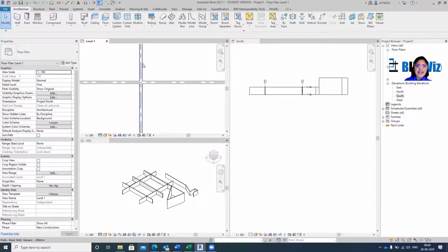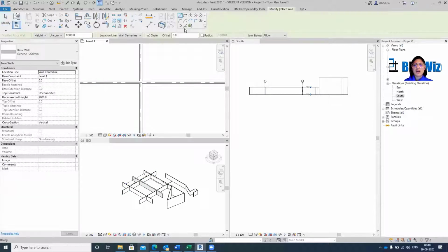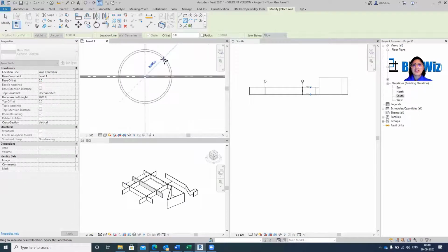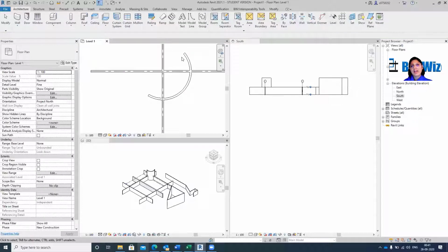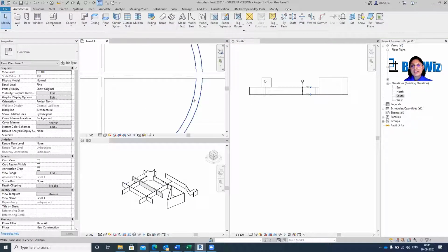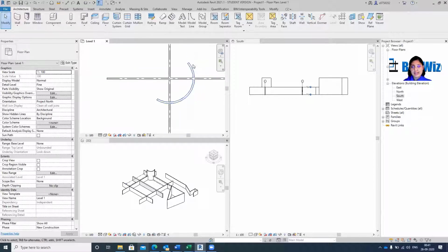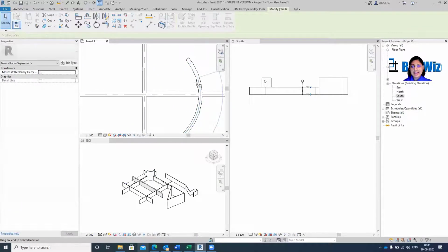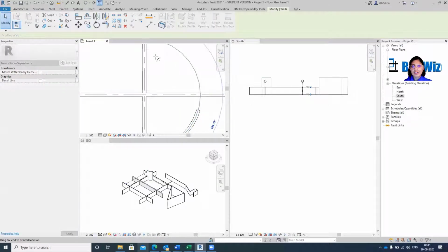Let's come back to this. So we could select the wall, we can draw a curve, go to wall, we can draw a start, give it a radius, and then I can draw the wall that I want. You will see that when I drew this wall, it did not draw itself over it. It just made this join here really nice. Now, if I go here, I can extend this wall like this. It will follow the curvature.